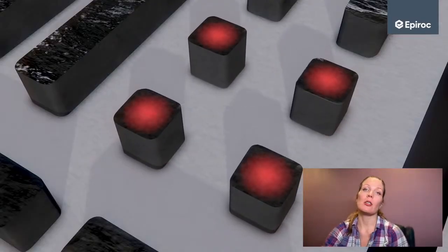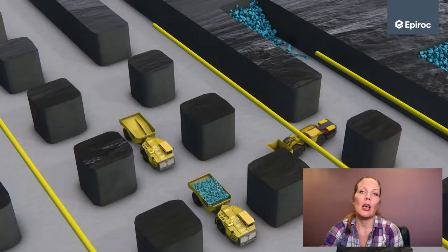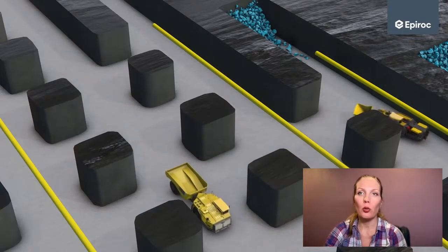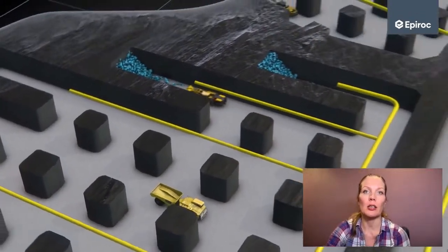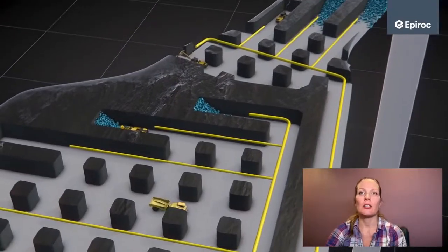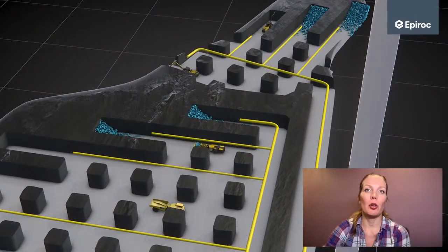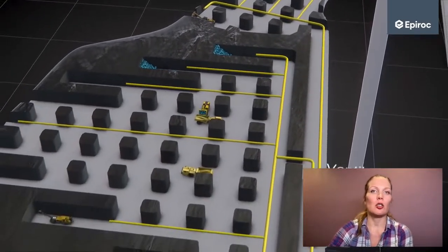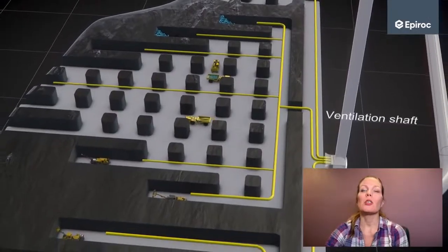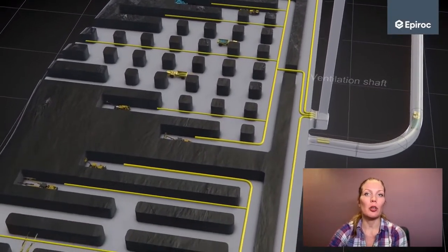Backfill strategy is also an important nuance. If the optimizer marked a cell as requiring unloading of adjacent pillars, the plan inserts a partial or full backfill or postpones extraction of neighboring cells until the fill reaches design strength. For larger panels, it often helps to introduce a block panel rhythm. The panel is divided into sub-panels, each treated as a small self-contained project with its own logistics, which reduces equipment hauling and keeps production more consistent.